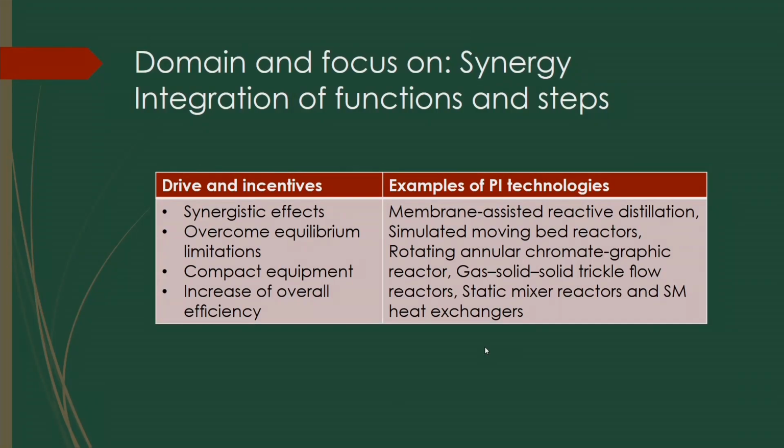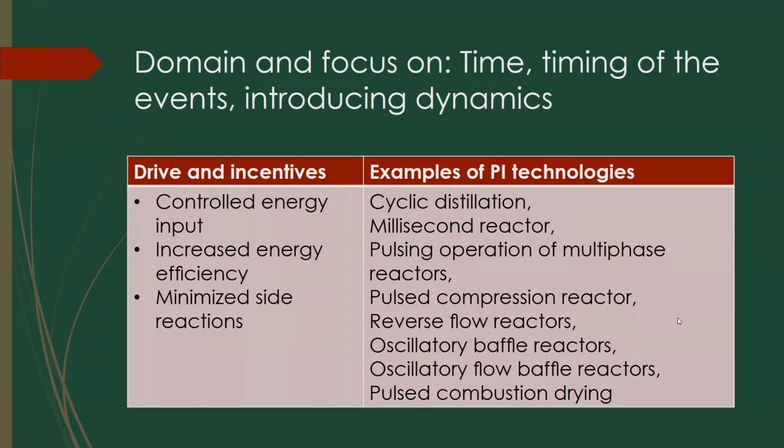Membrane assisted reactive distillation is a conjugated, or integrated, unit where process intensification is done. Some other processes are gas-solid trickle flow reactors in downflow systems, which are mostly used in the petroleum industry for catalytic cracking and obtaining several petroleum products in a trickle bed reactor. Controlled energy input is also an important intensification strategy for chemical engineering processes, like cyclic distillation and millisecond reactors.